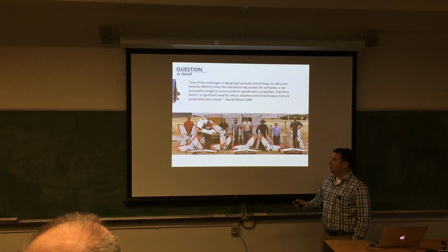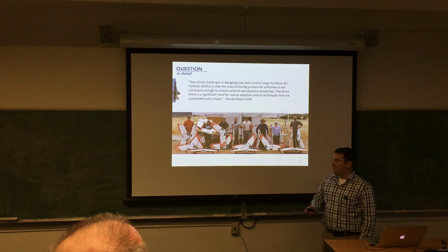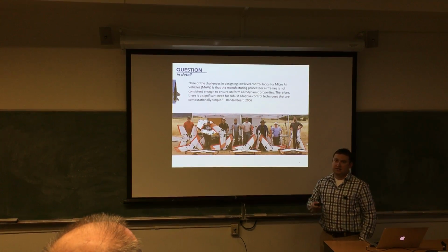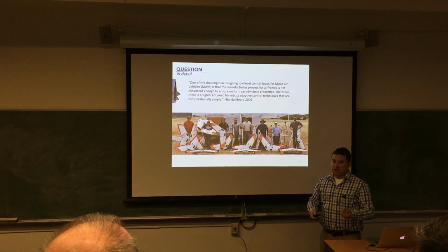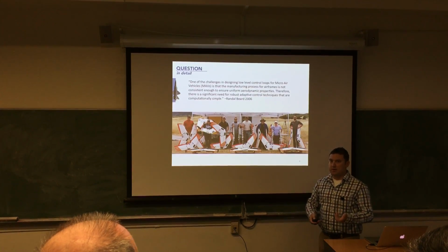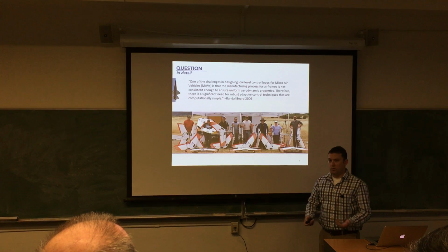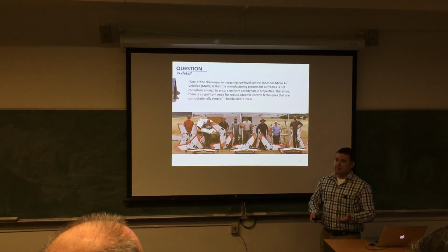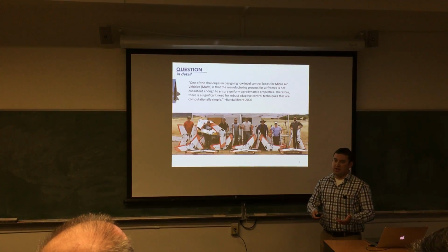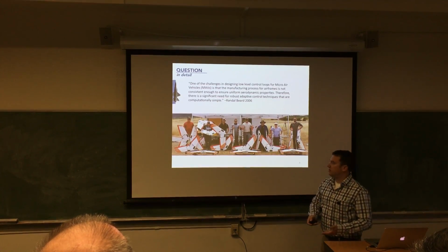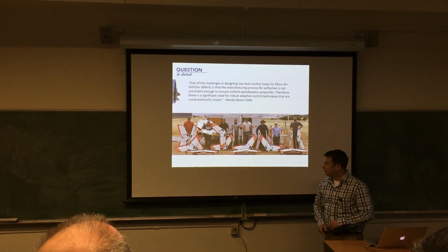The engineers that were on this project under Tim Chung very meticulously had to check center of gravity, aileron deflections, etc., because the build tolerances from the factory that made the 100 airframes just weren't adequate. And so, again, is there a flight controller that could be utilized to nominalize that behavior?